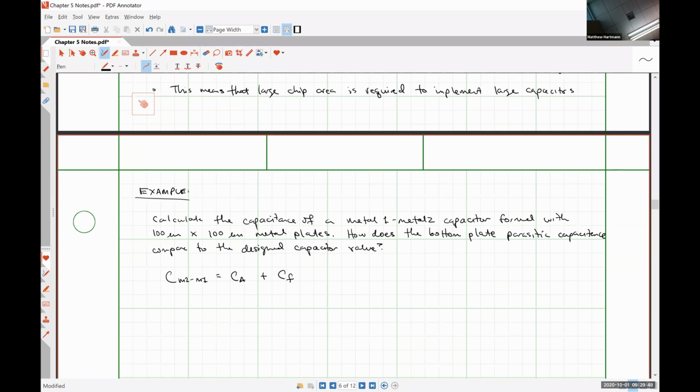So it's likely that since the poly 1 and poly 2 capacitors are physically spaced so close together, like on the order of a couple of nanometers versus the order of hundreds of nanometers, the fringe fields aren't dominant or even really present because the electric field is so well maintained because the distance is small. The further you get the plates apart, the more the fringe fields are going to allow to try to expand out from the plates. All right, so